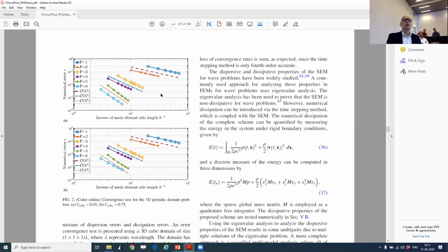But if you would solve a room like this one, and you would apply a mesh, then you need small elements depending on what detail you decide to model. But if you have small elements, and you have the high order in those small elements, your time step gets very, very small. Indeed. So it's not as promising as it might look in my perspective if you solve realistic rooms.